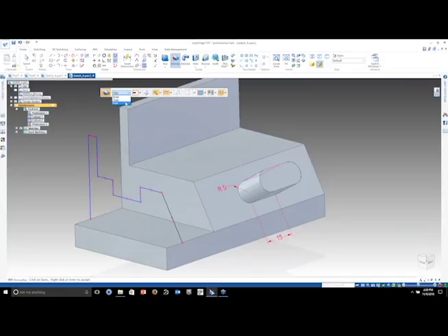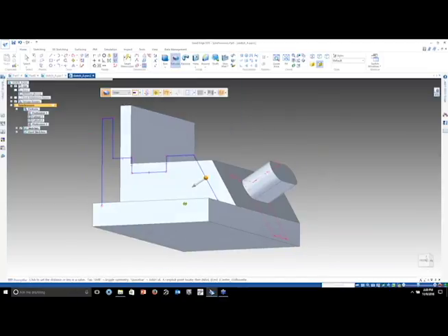So I'm going to do an extrude. You know, typically you'd grab a face using the regions to grab a region. But in this case, I'm going to do an extrude. The reason why is because we have some options. Here we have single, chain, or face. I can't use face because I do not have a region, but I can use a chain. So I'm going to say chain. I'm going to go ahead and grab that sketch.